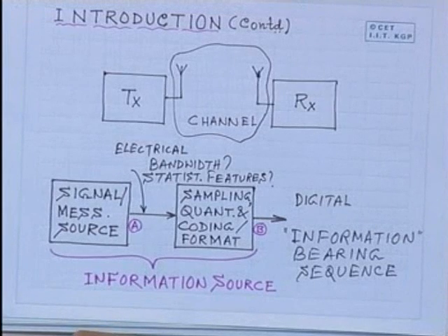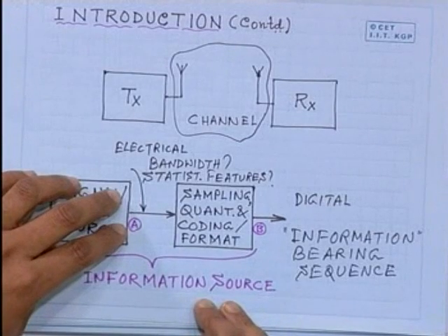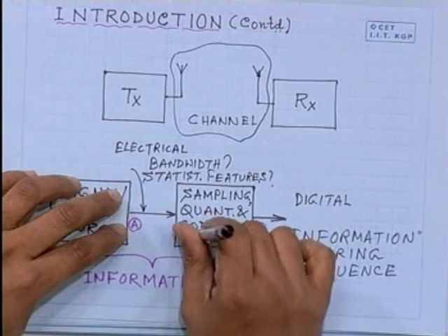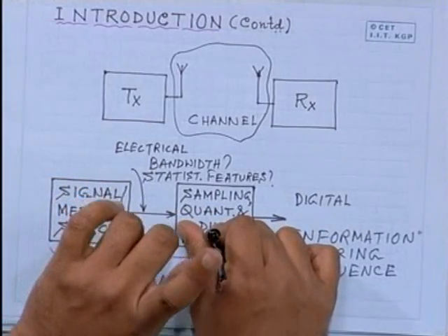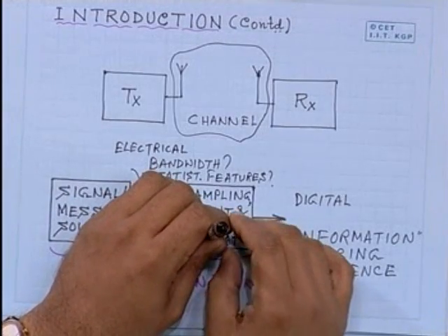Can you guess why? See, if the signal is a speech signal, and if sampling is done at a pretty fast rate, then the difference between two consecutive samples usually will not be very large in amplitude. Very small. It is not deterministic, but usually if I sample very closely and the signal bandwidth is not very large, as we know is up to 3.4 kilohertz, in that case the difference between two consecutive samples need not be very large really.